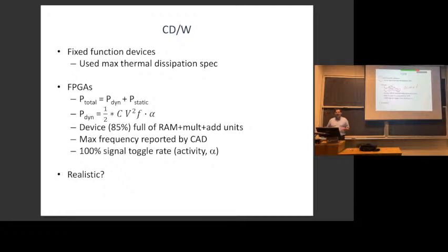The way it goes higher than 1 is if you have some gate that changes a bunch of times in a clock cycle, which can actually happen. It's called glitching, where the inputs of that gate change multiple times in a clock cycle and its output changes multiple times per clock cycle. It's wasteful. You generally don't like it. But it does happen in things like XOR gates. If you have a 3-input XOR and all the inputs change at different times every clock cycle, the output of that XOR will change multiple times per clock cycle. So usually it's less than 1, but technically it can be even higher.